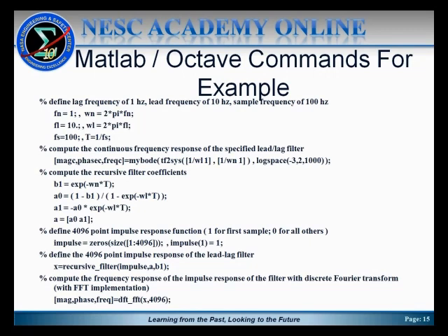Then I'm going to pass that impulse response function into that recursive filter, and the output that I'll call x here is the filtered value of that impulse response. You can use that to compute the magnitude and phase of that lead lag filter. The recursive filter that you see there is not a built-in MATLAB function. Again, that's just an implementation I've constructed for doing recursive filters as described a couple of slides ago.